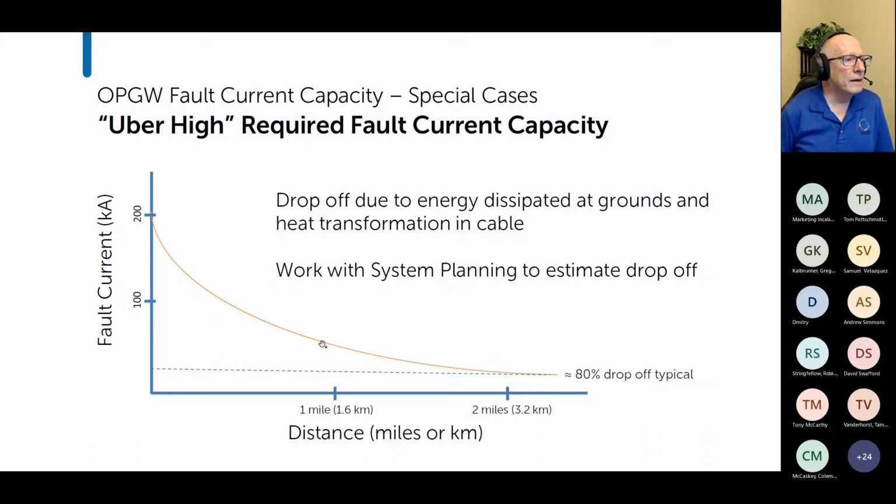I should also mention that in that condition, or if a fault current did happen and you chose to just use a smaller cable and take the risk, the cable's not going to burn down for 1 to 2 miles. The cable is going to tend to burn down or be significantly damaged for 1 to 2 spans. So backing up that concept of taking a calculated risk.